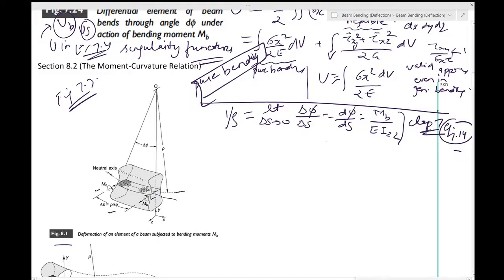One of the things is that we would want to maintain this exact orientation throughout this chapter, just so that the development of the theory is consistent throughout, and the long dimension of the beam will always be in the x direction. Okay, and the bending will take place in the xy plane, usually about the z axis. So about this axis the bending is taking place, and under these circumstances it will cause no ambiguity if instead of the symbol I_zz we just use I.